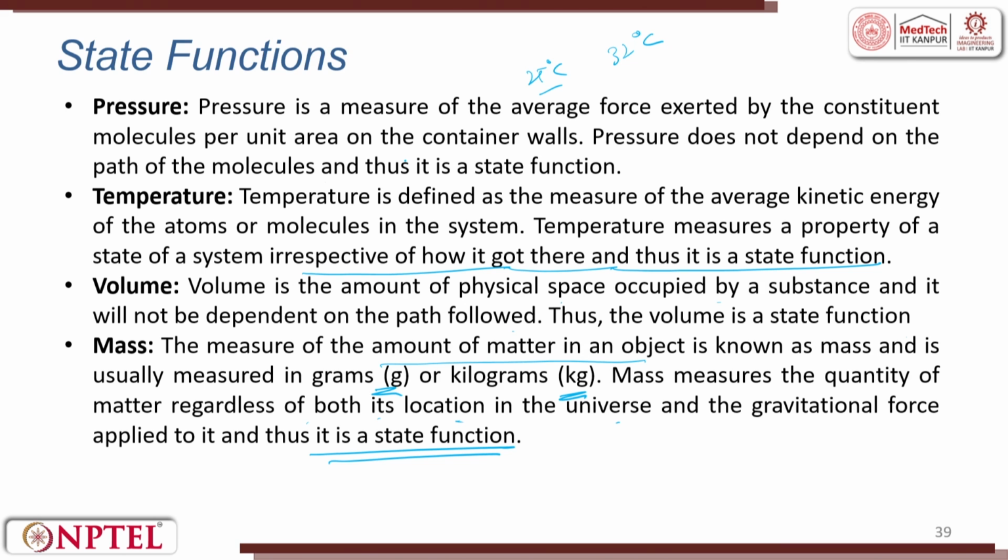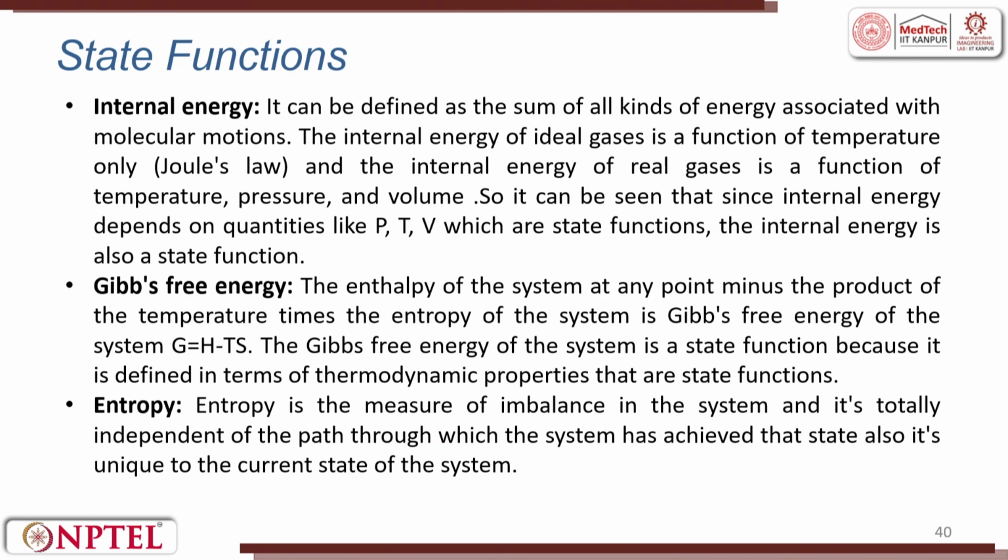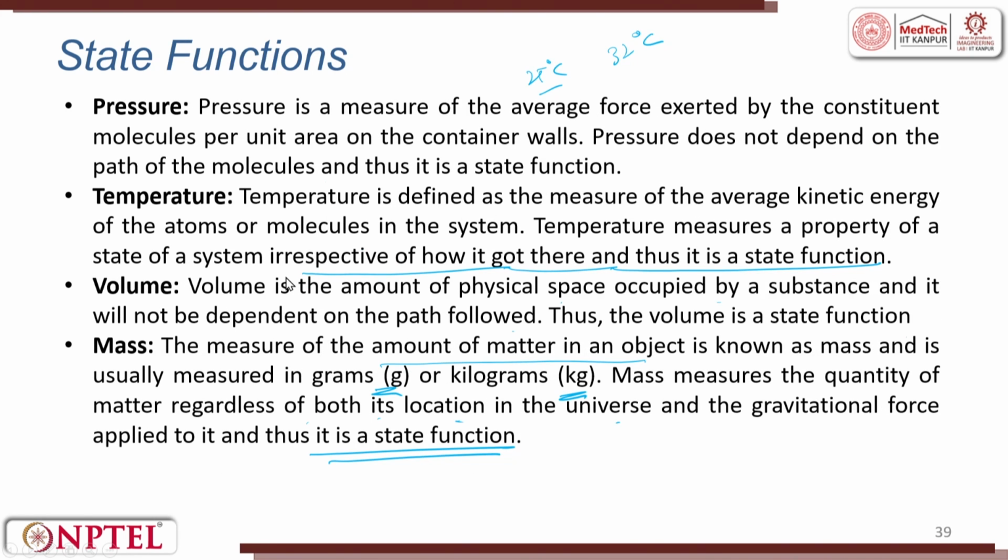I am trying to tell you what all the state functions are. Then it is internal energy. Internal energy can be defined as the sum of all kinds of energy associated with the molecular motion. The internal energy of an ideal gas is a function of temperature only, according to Joule's law, and the internal energy of a real gas is a function of temperature, pressure and volume. Since internal energy depends on P, V, T, which are state functions, the internal energy also is a state function. So we have seen P, V, T, M.